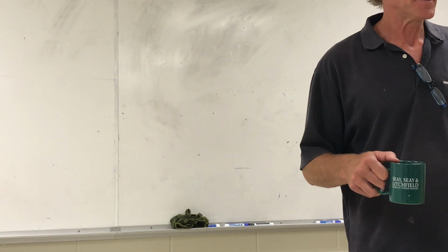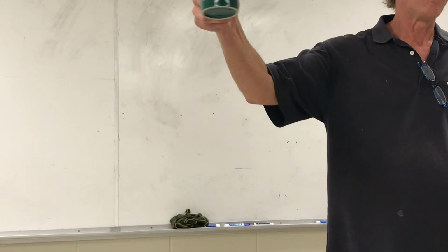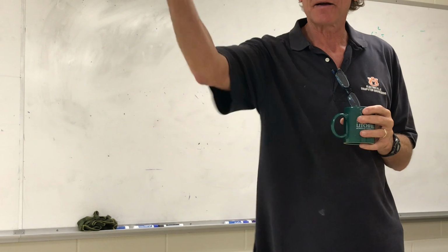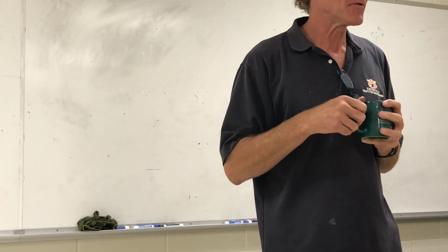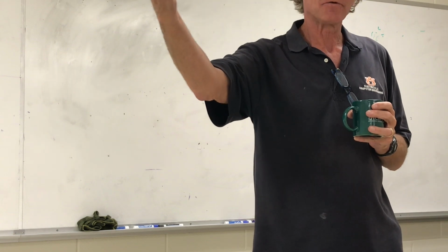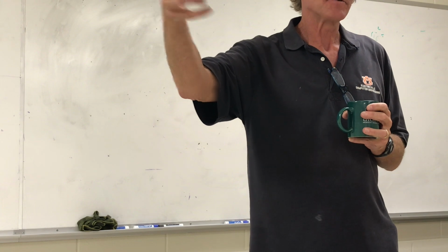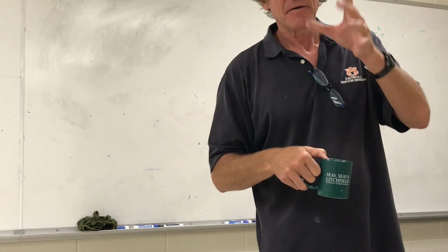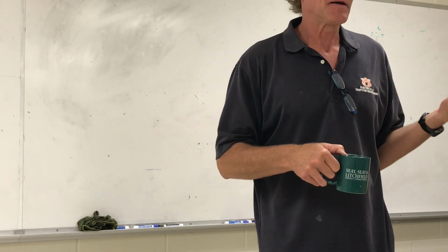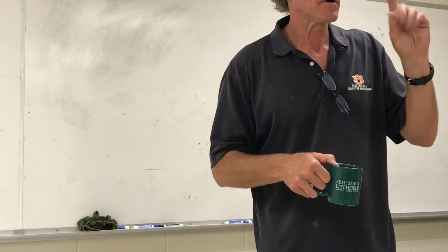Here's something. You've got a dipole antenna, and you want to transmit through a wall to the other side, and you've got another antenna over there, and you have to come up with some electromagnetic model for the wall. That you can look up on Google. You can look up all sorts of things for the wall. This is EMC. And you want to do something over a frequency range. So what's the minimum power to get, say, a fairly good footprint on the wall using a type of antenna that would do it? That would be basically a loop antenna or a short dipole.